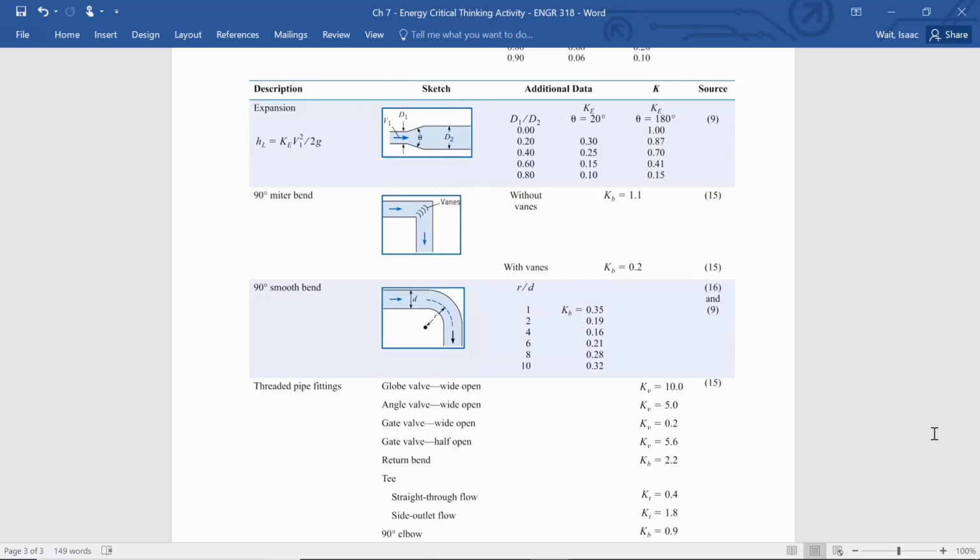And so there'd be less energy loss if the bend wasn't as abrupt. So this 2 means that the radius is 2 times the diameter. Rather than having the pipe change so quickly, this is maybe what an R to D of 1 would look like. If it was instead 2, then it's going to be a more gradual transition. Okay, so now we've got here R to D of greater than 1.